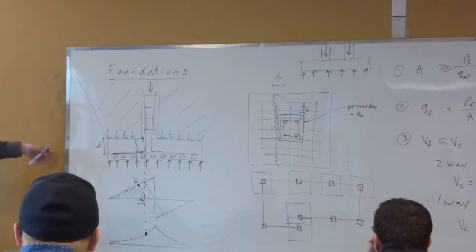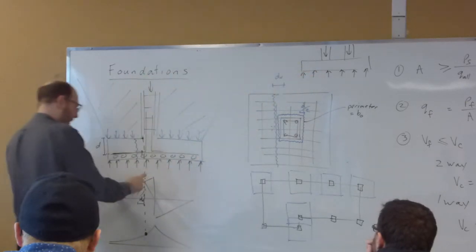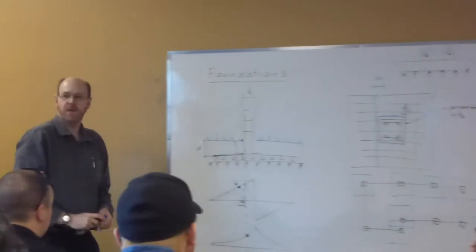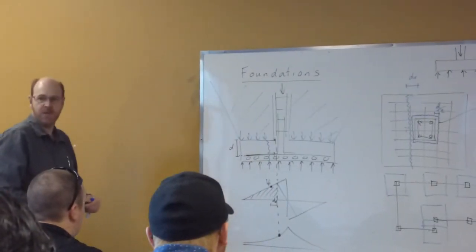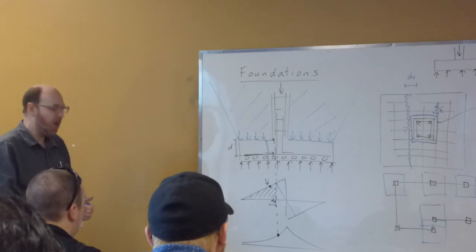So it alters the shape of your shear and moment diagram, but the process is we're still going to have on the left-hand side here, we still have this triangular shape. Find the area of that triangle and come up with our moment. That process doesn't change. So we don't really worry about the fact that we're overlapping.